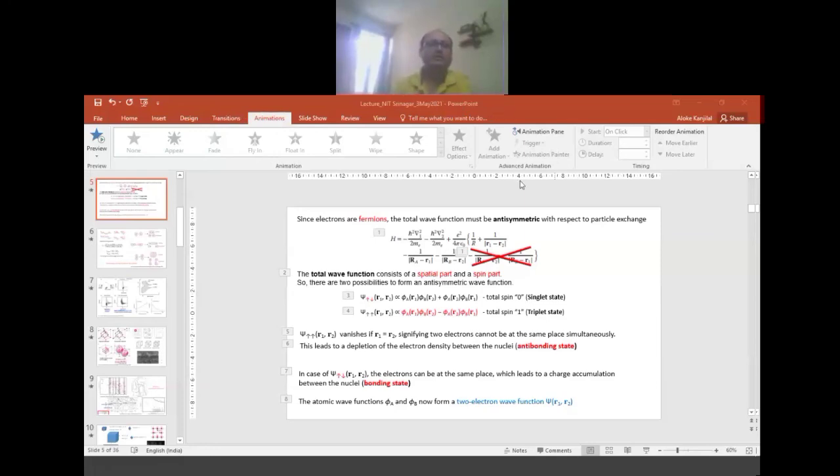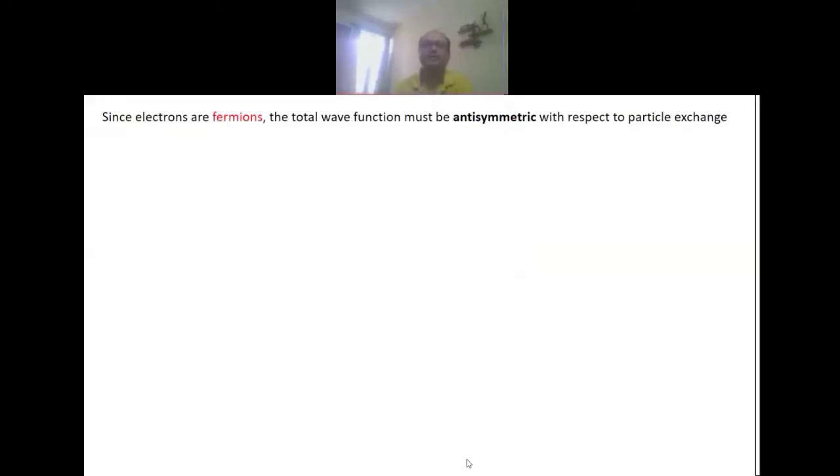So here's the lifetime. The lifetime has 2 different components, non-radiative and radiative parts. The response is made of these 2 components, and they are inversely proportional to the lifetime and the population of the electrons. If you go into details about this, you can find out the quantum efficiency of those devices. If you get a good electroluminescence from any device and use it for LEDs, you know that you should have a better quantum efficiency. I just quickly show that we have given a model called the inverse energy transfer model, which is also published in APL.